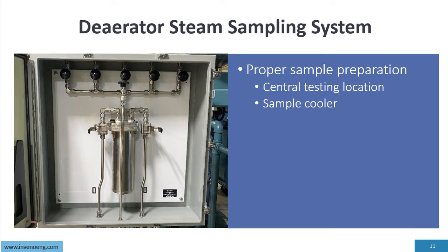The other thing for deaerator sampling, or doing the test for dissolved oxygen, you have to have proper sample preparation. Typically, the best is a central testing location and a proper sample cooler. The other thing is making sure that all the valves and components meet B31.1.